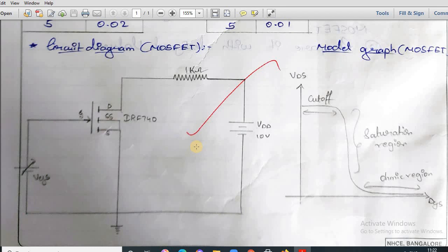The 3 operating regions of MOSFET are cutoff, ohmic region and saturation region. In the cutoff region, MOSFET will be off and there will be no current flow through it. In this region, it behaves like an open switch and is thus used when required to function as an electronic switch.